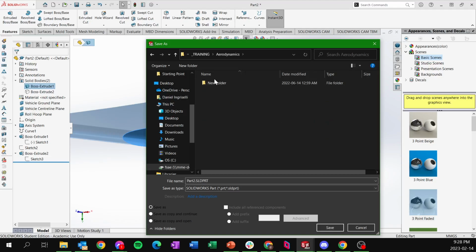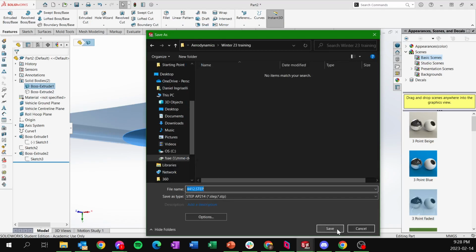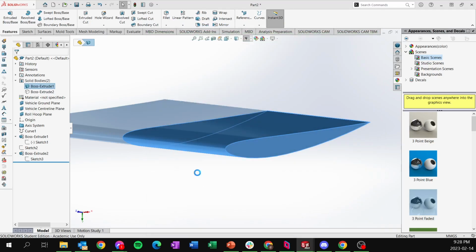Training, aero. We'll call this winter 23 training. Okay, and then you're going to want to save it as a STEP 214. I have heard some people like to use Parasolids, and I guess that's fine. I prefer STEP. Don't ask me why. It's just what I do.